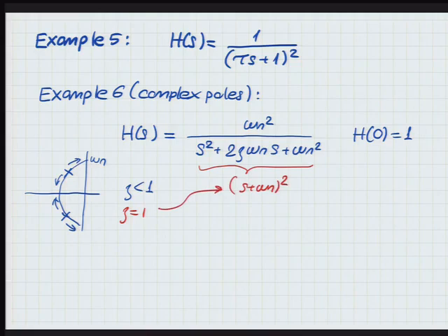So that means now you have two real poles that are both at negative omega n. Okay? So how do I draw the frequency response, the Bode plot, for this? No matter what zeta is, I pretend it's 1. Okay? It's pretty egregious as an approximation, but it's a good approximation if zeta is close to 1, so if you have a well-damped system.